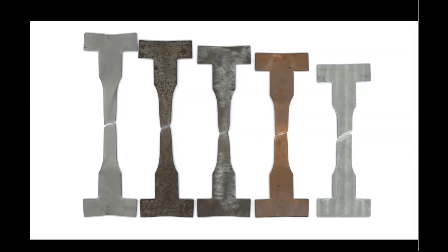And you could use words such as shear fracture, shear angle fracture, shear lip, or defined fracture. Okay. What you also see in the aluminium sample is that there is almost no visible necking. Like if I contrast it to steels, steels have necking. Aluminium, I don't see.